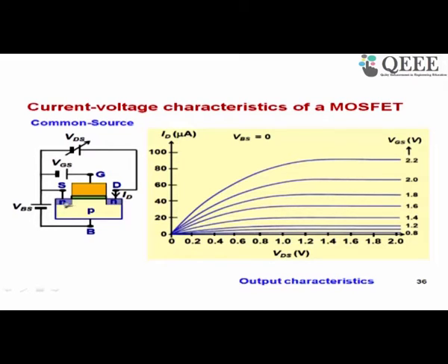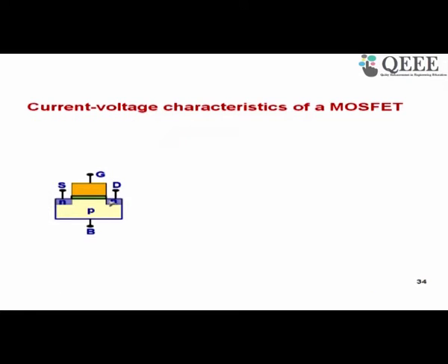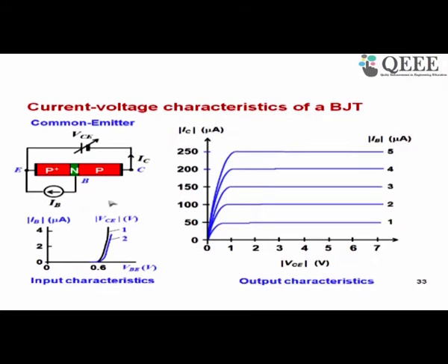In this case this is an NPN transistor where the current flow is because of electrons. Let me take you back to the bipolar transistor slide, and you can see there that this was a PNP transistor. You can have a PNP or NPN transistor, right? So here it was a PNP transistor. That is why the collector current was outward. If you take an NPN transistor, the collector current would be inward.